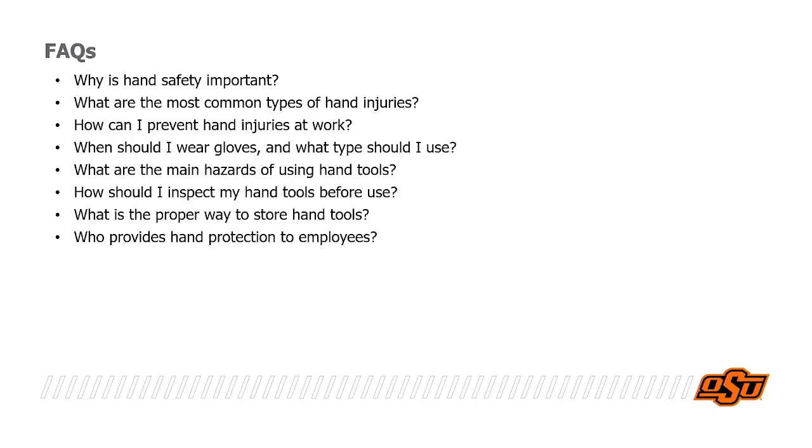What is the proper way to store hand tools? Very simply, when you're storing hand tools, you will make sure that number one, they're not plugged into anything. Number two, if they happen to be a battery-powered tool, remove the battery. And the other thing too, as far as storage of the tools, make sure that you do not hang the tool by its cord. Always just lay the tool down. You can wrap the cord up a little bit and then place it directly beside the power tool itself.